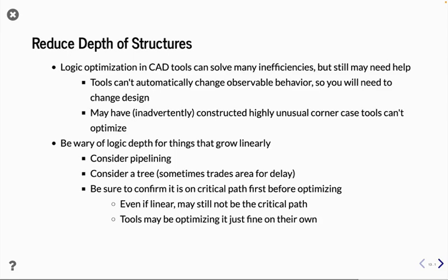And so if you're not careful, sometimes you make something that's hard for the tools to optimize, and they're kind of stuck with it, and they have a hard time. Other times, especially with Chisel, the emitted Verilog from Chisel may seem really inefficient, but the CAD tools recognize what it's doing, and they can optimize that for you really well. So for example, if you do a Vec in Chisel, when it gets turned into Verilog, it's actually turned into a mux per element. Basically, if I have an 8-element Vec, it's like, hey, is this element 0? No. Is this element 1? No. Is this element 2? No. It's like this linear, unbalanced tree of muxes that seems really bad, but most CAD tools realize, oh wait, I see what's going on. Do the right thing, have one big mux, and it's handled.